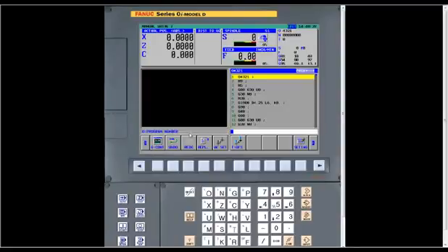Okay. Early in the program, one of our attendees was interested in showing a roughing cycle for a hollow cylinder. So maybe you can just touch on that briefly now that we're this far along. They wanted to do a roughing process for a hollow cylinder? Oh, yeah, that's no problem. When you're doing a turning cycle with a hollow cylinder, say you're boring out the inside of it, the last move that you would make would go down to the smallest size of that hollow cylinder, and then the control would know that that was where the stock would be removed. So it's very simple to do that. It's just based on the geometry that you described for that hollow cylinder within the turning cycle. That's how you do that.